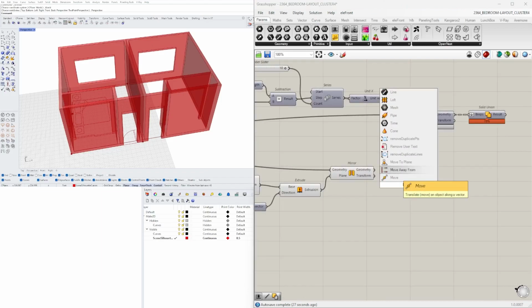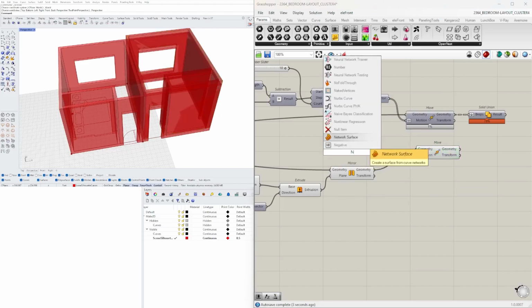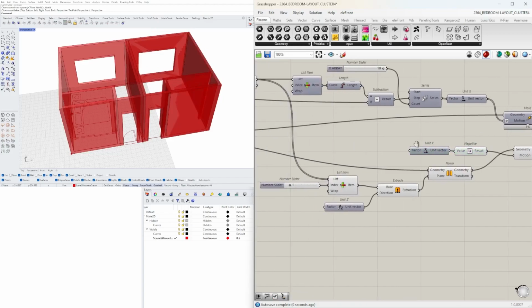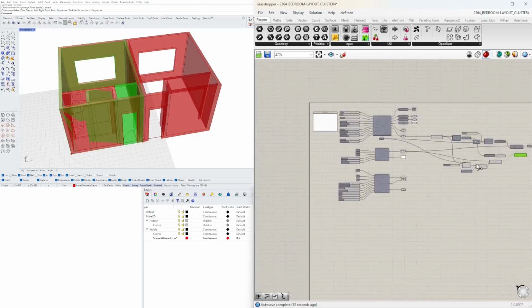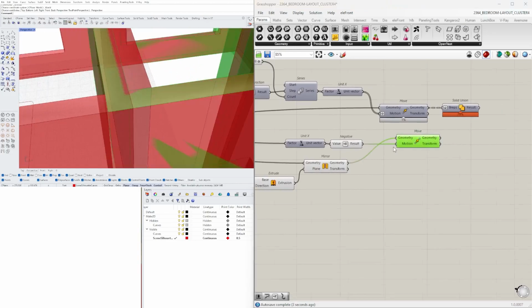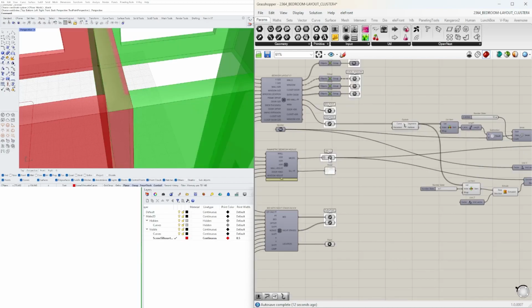We'll go to move, the mirror geometry, and the negative X. And we'll be using the X factor. Gotta use 3.5. That's what we'll use, this number. Plug it in here. So it moves it back by 3.5. Now we'll hide this part. We have these two as our module now.